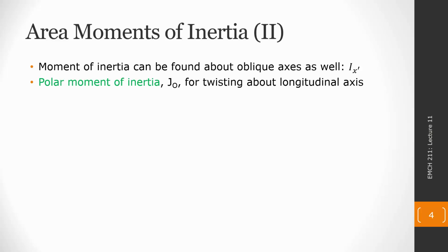And I'm going to use for this course the term moment of inertia and area moment of inertia interchangeably. Specifically, the things we're going to be calculating are area moments of inertia. As we're about to see, there are other kinds of moments of inertia. But in this course, the only moment of inertia we're using is the area moment of inertia, so that's why I'll use it for shorthand.